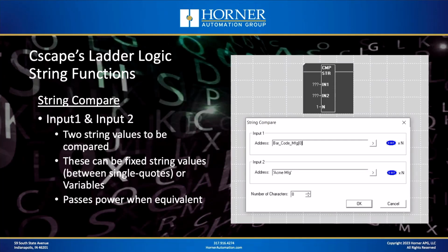So where is this useful? Well, really, anytime you're comparing two strings, which could be because you're monitoring an input that's come in from a barcode or an RFID reader or some sort of serial communications, and you're looking for a specific pattern of characters, and if you see that pattern, you want to pass power flow and move on to the next part of your processing. So that is the string compare function.